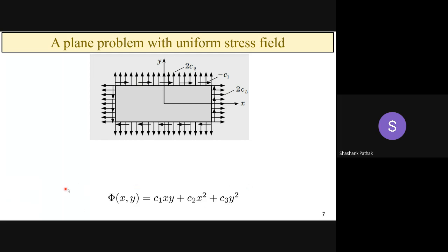This is an Airy stress function. So from where did it come? It came basically because this kind of plate problem can be solved using this kind of Airy stress function. This is already available in the literature, and from there it has been taken directly. These kinds of functions can be developed using some observations, because here you are solving the plane elasticity problem using a heuristic approach.